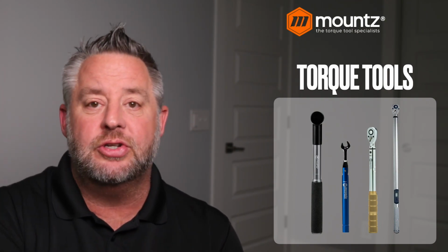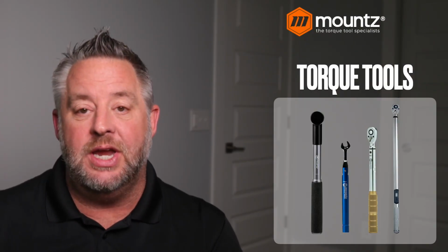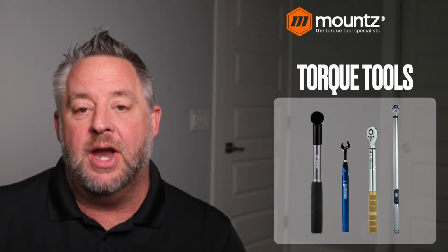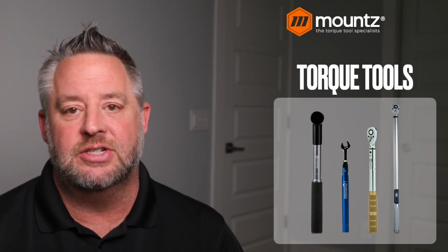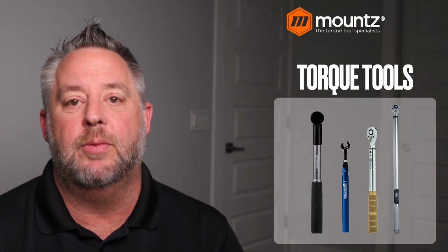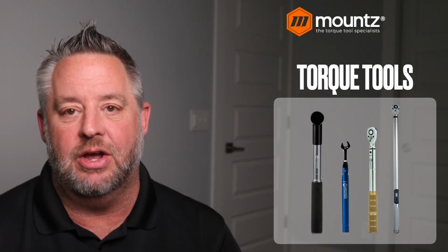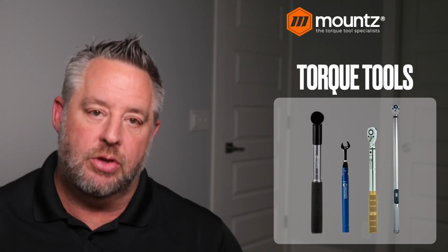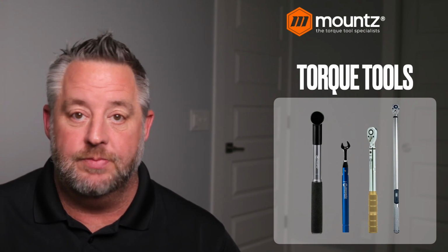If we move closer to the head, we're going to be adding more torque. And then if we put an extension on the end of the tool and pull from there, we're actually producing less torque. And so that's another thing to consider when looking at torque wrenches. We want to make sure that we're pulling it from the right spot, again, because the fulcrum point is inside of the tool, not at the very end. Although there is torque output at the end, it's not the fulcrum point for those particular tools.